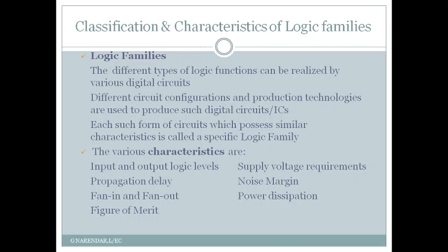We will look at the various characteristics that are important to understand the circuits of a logic family, and here we list the important characteristics: the input and output logic levels, supply voltage requirements, propagation delay, noise margin, fan in, fan out, power dissipation, the figure of merit.